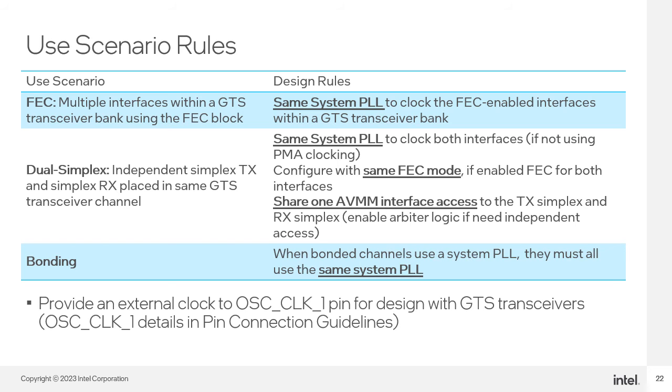For bonding, when you bond the channels using a system PLL, they must all use the same system PLL. On top of that, for those simplex cases, you must also use the same segment if you enable the FEC for both the TX and RX.